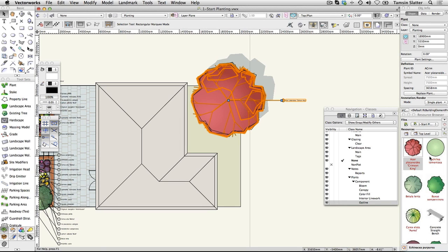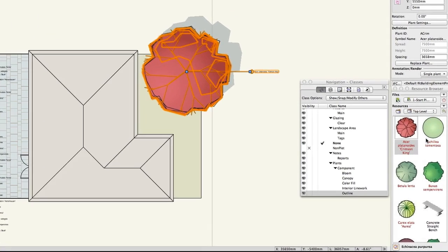You can also make your own if you have an image editing application and the skills to remove the background from a plant photograph. Image props are flat images stuck onto two crossed 3D planes. They have a transparent mask around them so that their background is obscured and they cast the correct shadows when rendered. The following steps are dependent upon Renderworks being part of your licensed installation. If you don't have Renderworks, you can skip these steps and move to the following exercise.